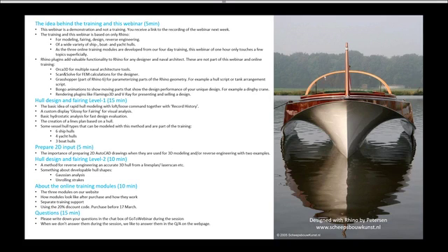As I gave more and more training, I decided in 2012 to develop actually a hull design and fairing training, because I saw that there was a need for practical tools how to model a decent ship hull in Rhino. What I see a lot in the maritime industry is that people model ship hulls as a patchwork of surfaces. And when it is successful once, it is a very difficult job to edit a patchwork of surfaces when the client says, I want it longer or more volume in the bow area. So the rapid hull modeling methodology enables me and other people to create a very nice hull in little time that is easily editable.